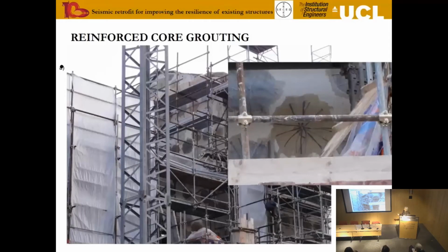You can see this wall, there is one every half a meter, and these are made with FRP strands, which are then opened up to provide some anchorage. But basically, you are drilling a hole in the masonry at a distance of less than 300 or 400 millimeters, for the whole wall.